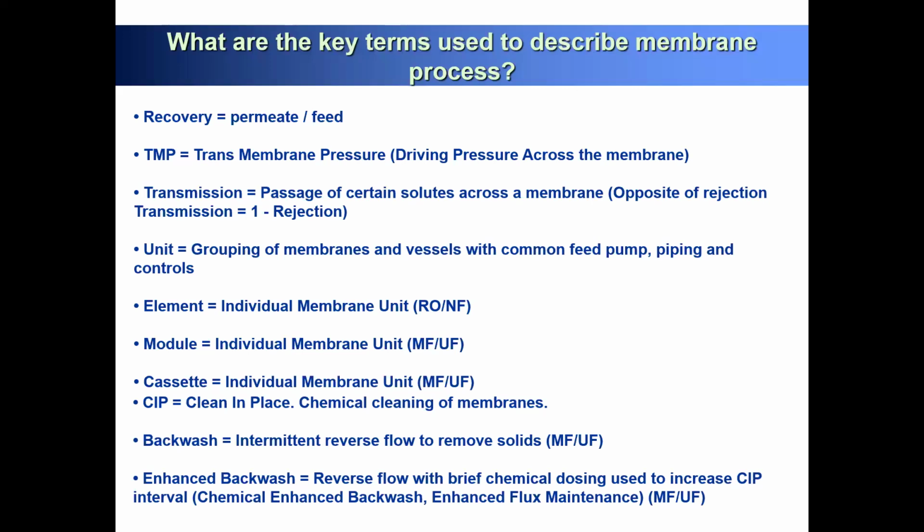So you can see from your assignment, specifically look at the boron concentration in your seawater. If this concentration is less than 0.5 milligram per liter, we need to make sure it does not go over this concentration.